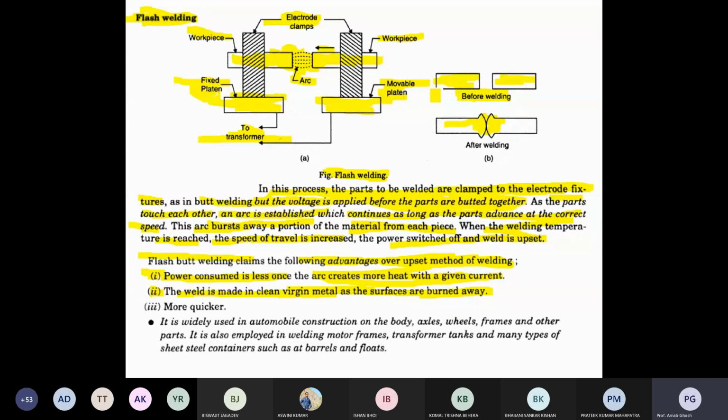In the case of machines, you know we use oil impregnated paper insulator. How do we test that? We do a vacuum test. There is a vacuum tank, and we directly immerse all those insulators and machines inside the vacuum tank in the workshop.